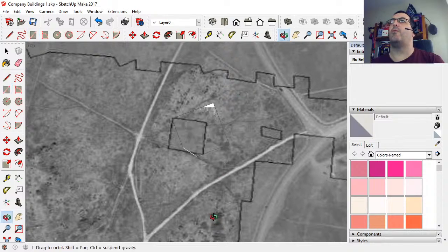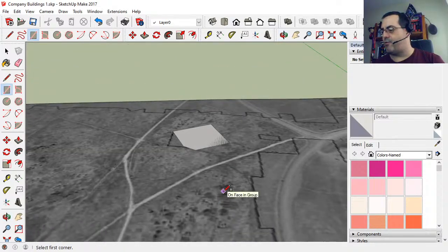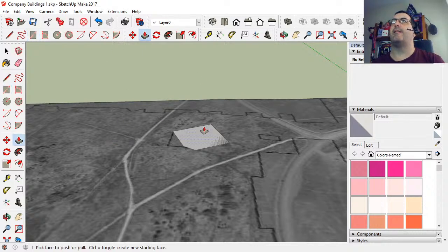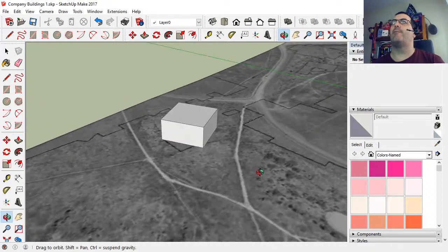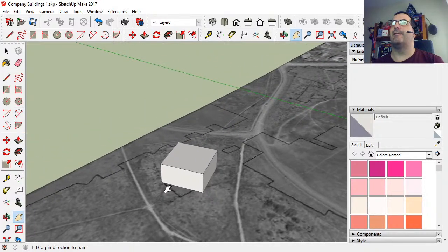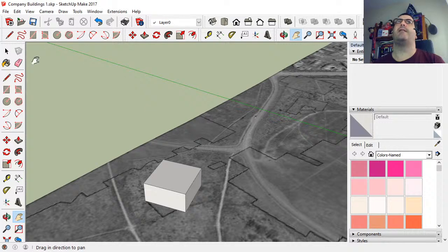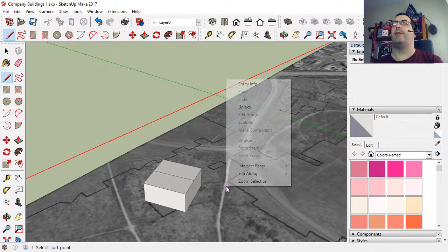If we go back to our 3D view, again, drag with the middle mouse button, we can then start using tools like this, for example, and bring our block out of the ground, so to speak. It's still only an ugly block, right? Well, because we've now got it in a package like SketchUp, we can make use of the many things that SketchUp can do. So, for example, if I use the measurement tools and get a line that's exactly across the midpoint.